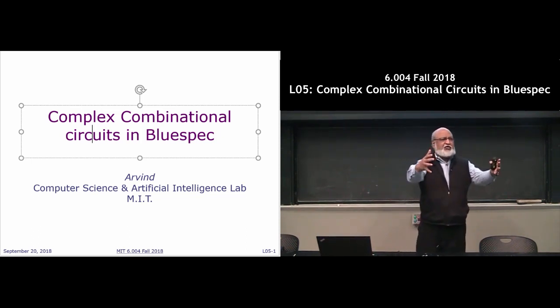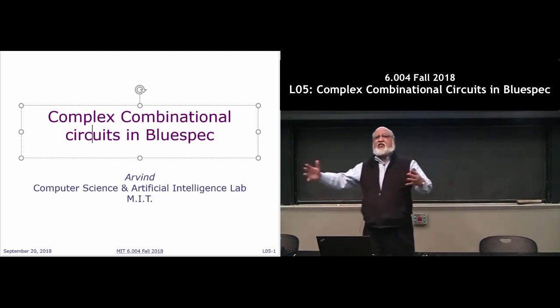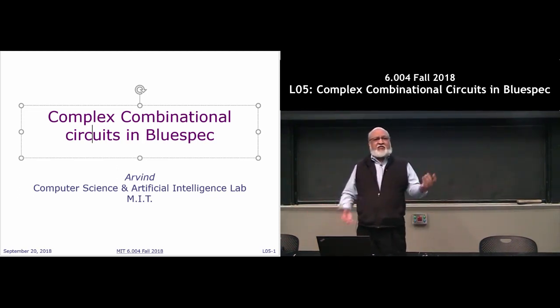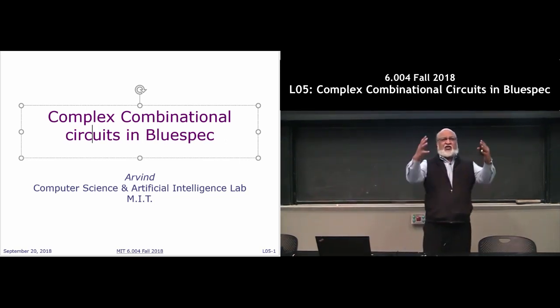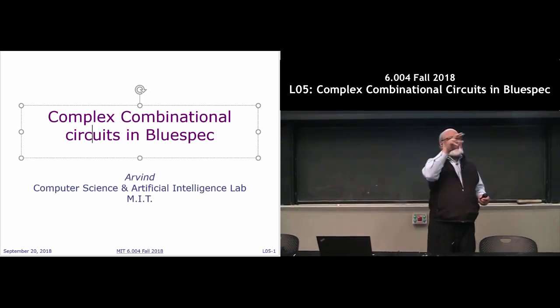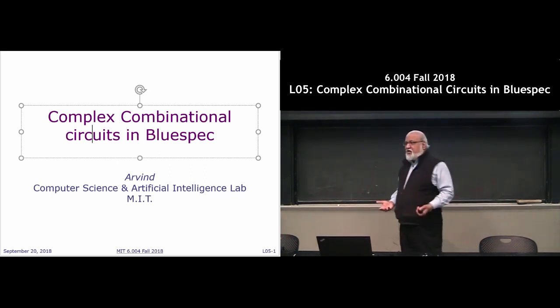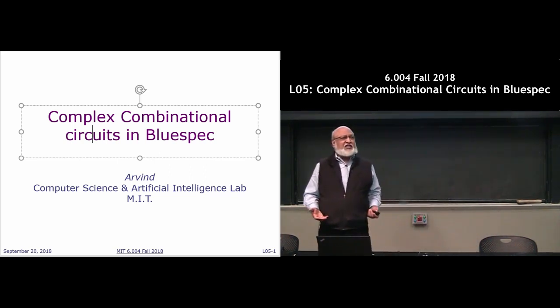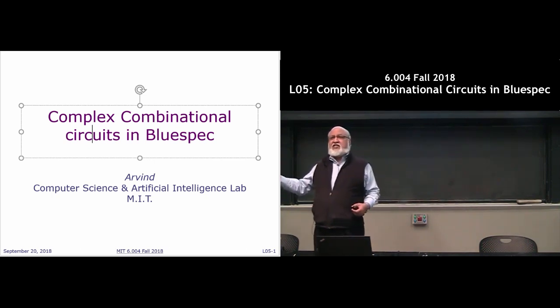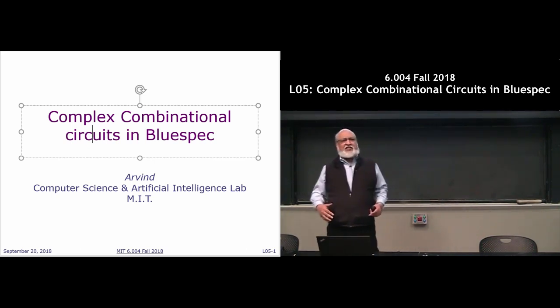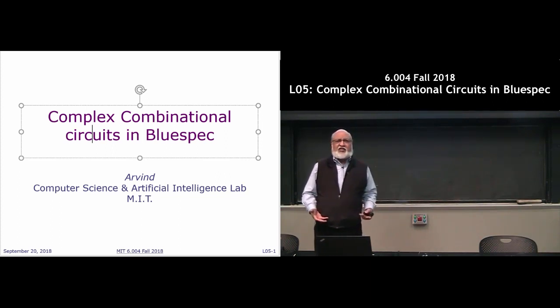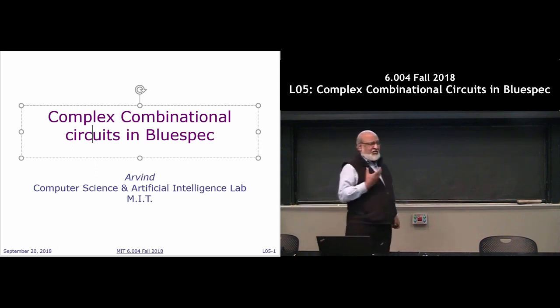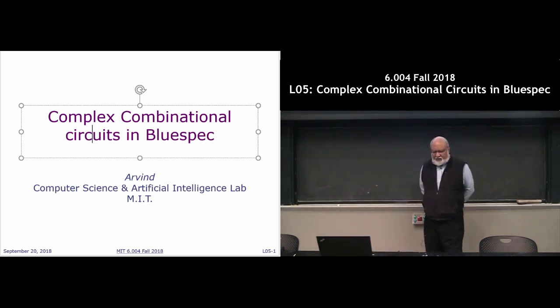You start out with some Bluespec description, and we want to get this complex picture out of it, right? Circuit, where all the things are connected. But we also want to figure out its computational meaning, that if I put two numbers in it, what is the answer that comes out? Because that's how we debug it. That's how we find out whether it's actually doing addition or not, right? And rather than resort to some other things, we just say, we know the meanings of ANDs and ORs, and if we propagate it, we should know what these bits will produce at the output of the circuit. So that's the computational meaning of these things.